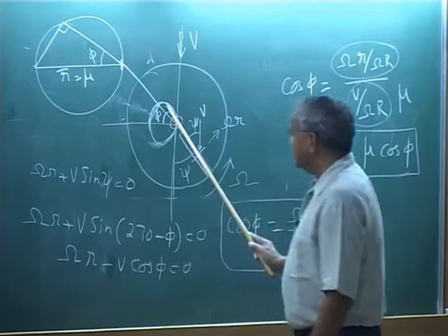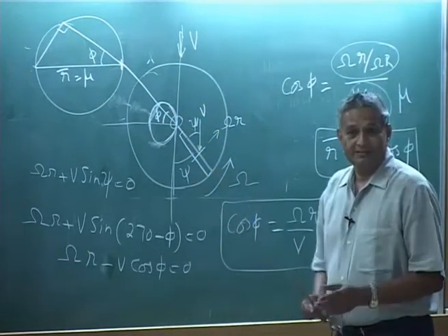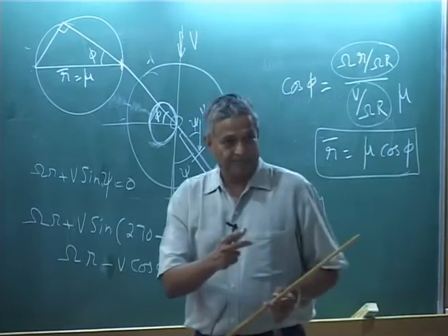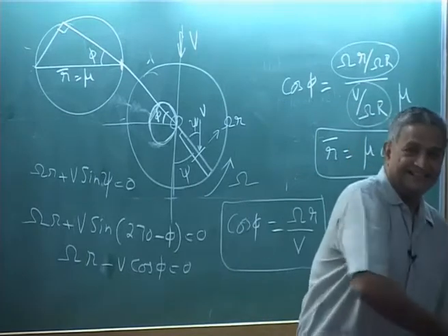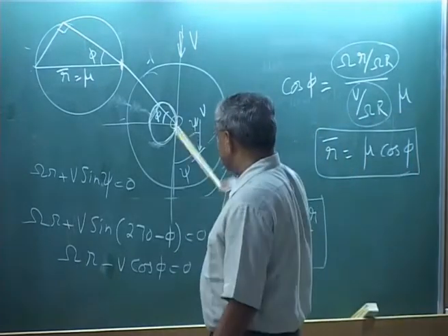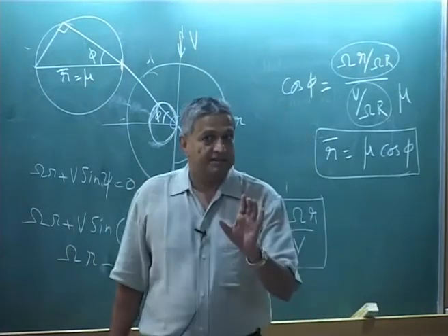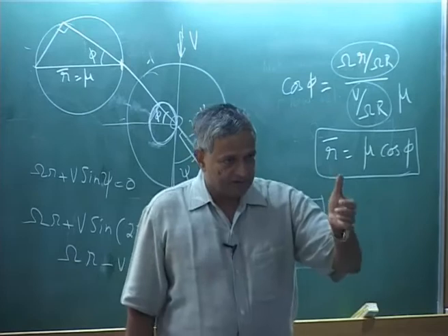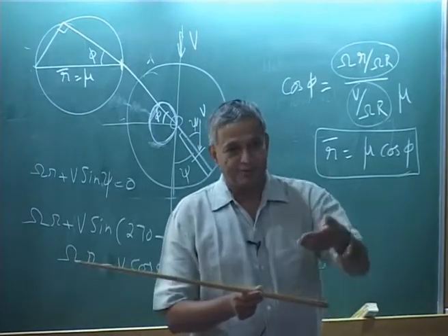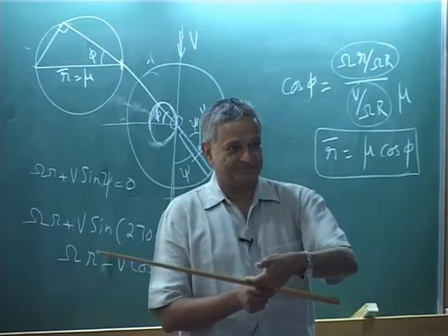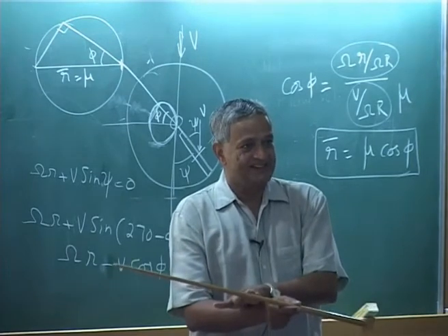That means this region, as you keep on increasing your helicopter velocity, will become bigger and bigger and bigger on this side, retreating side. So, you know that you will get the lift only when the oncoming flow is towards the leading edge, not when the flow is from the trailing edge. Okay.